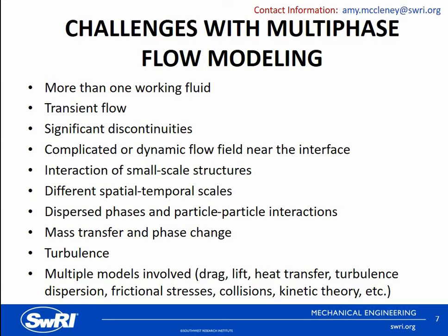So there are two big approaches to turbulence models. You have a two-equation turbulence model, where the transport equations for your turbulent kinetic energy and energy dissipation rate are solved in both space and time. An example of this type of model is the standard K epsilon model, or the realizable K epsilon model. You can also have stress transport equation turbulence models, which solve the differential equations governing the evolution of the tensor that represents turbulent stresses. An example of this type of model would be the Reynolds stress model.